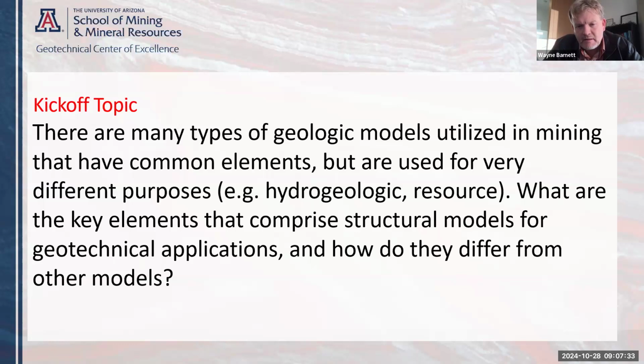So understanding the continuity of the structures and the properties of those structures, and understanding the overall pattern forms the basis of what you're going to use to build that model, and once you've got a model like that, then you can start to use that within geotechnical slope stability analyses. It's as simple as that. Very succinct. All right. Anybody else want to jump on that?